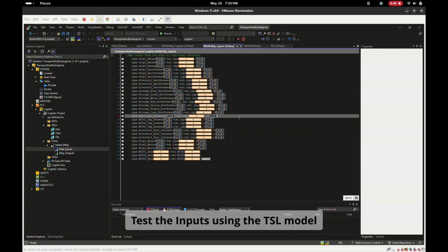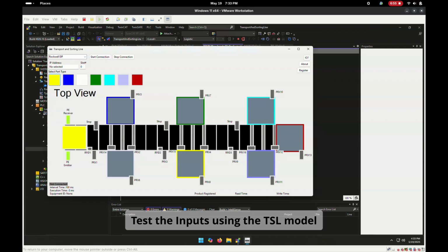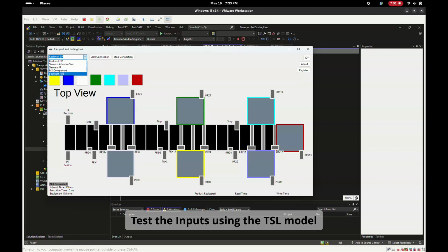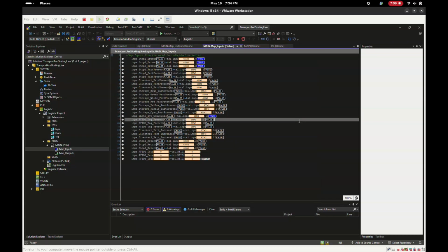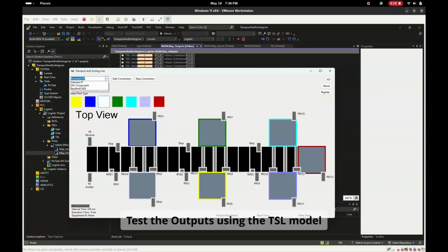Make sure that you are connected to the PLC online, and make sure to connect the simulator to the TwinCAT runtime. You guys can see a green indicator saying connected. That means that this process is connected, and we can see that some tags are coming in.